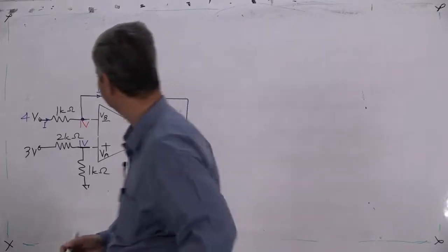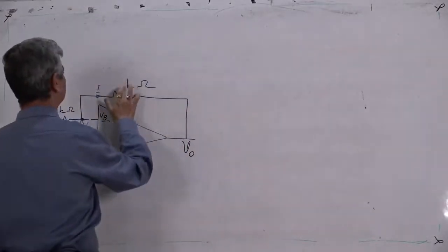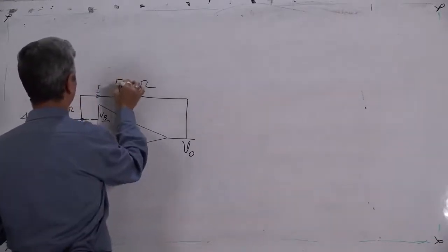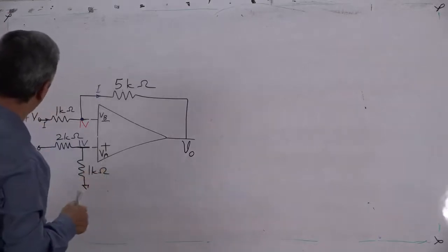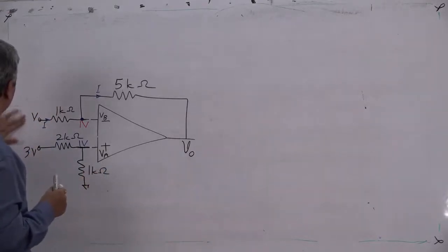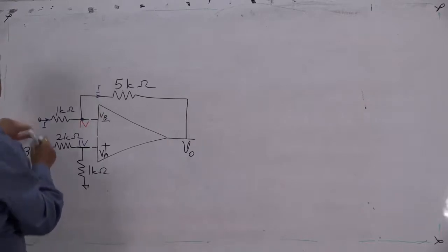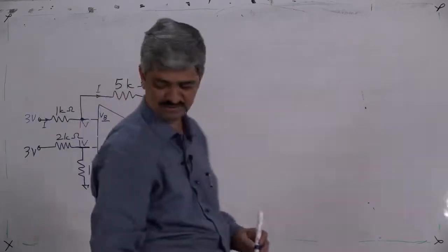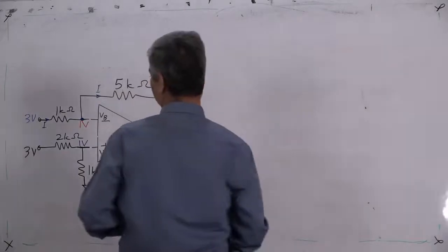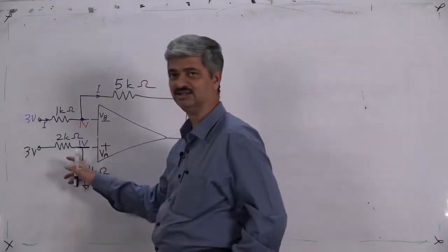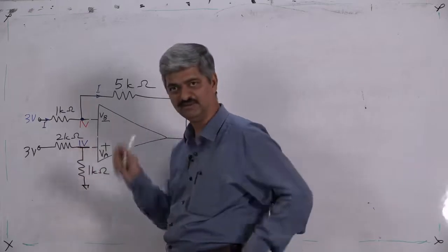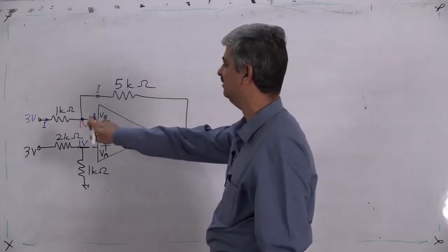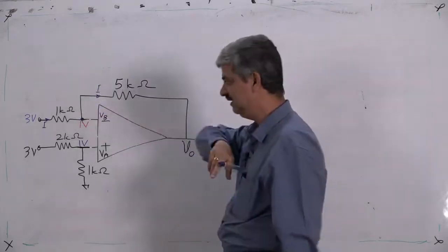So we make small changes, we make it 5 kilo ohm, and we make it 3 volts, and just this we keep the same so that not much change is required. So in that case, first step disconnection, second step calculation of VA, third step transferring VA to VB remains common. Then we simply take the fourth step, apply Ohm's and Kirchhoff's laws at the inverting terminal node.